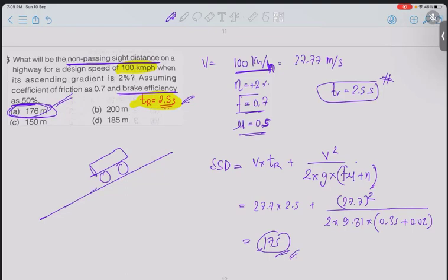You have to take 100%. Only for the super elevation calculation, we use 75%, as in step 1 also. But when you are talking about calculating the ruling minimum radius, then we use full speed. I think e plus f is equal to V square by Rg, we use this formula. Okay, thank you.